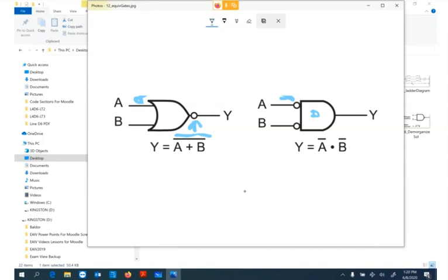And the same as B, but where this was a 1 before, now we've negated it, and it becomes 0. So we have no output there. But you notice how the bar now is over the inputs. So this truth table would be the exact same as a NOR. What would you call that? Two negated input AND gate. It doesn't really have a name.